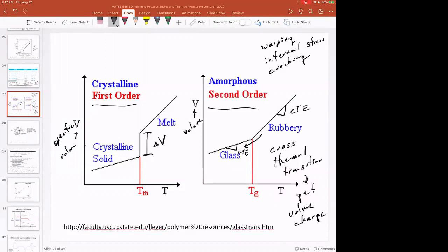And I think lots of people have a sense for what warpage is, but this is a scientific reason why it happens. And so when you talk to people who design additive processes, they're really concerned about what is the CTE mismatch, or what is the warpage of this material, or how do I dewarp a material, or how do I post-process to relieve stress or warpage.